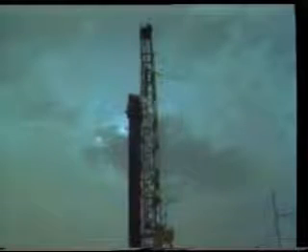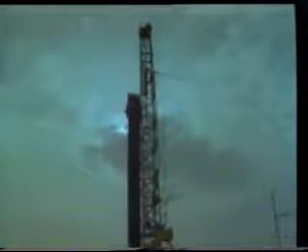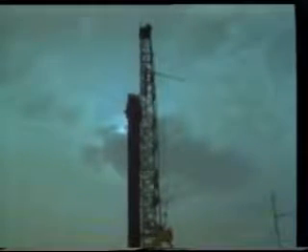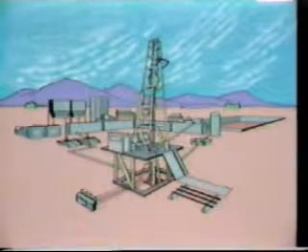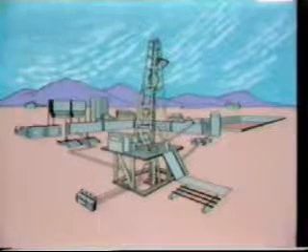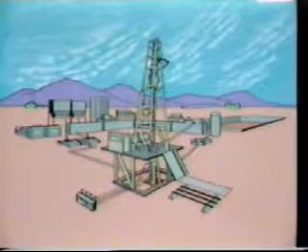Each of these drilling rigs, despite variations for a particular environment, still provides the means to perform the 4 basic drilling functions. In this respect, all drilling rigs are alike and really haven't changed much from the early rotary rigs. The 4 drilling functions are hoisting, rotating, circulating, and controlling. Each function is performed by several components, all of which fit together into a smoothly operating system for making hole.